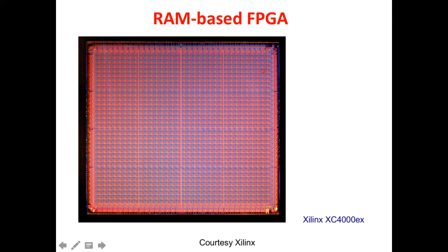And so typically an FPGA is extremely regular. The differences between the functions of the different blocks are written into the memory, so they cannot be seen by an image. In the previous case, the functions are encoded in the interconnections, and of course you see the difference by looking at the picture.